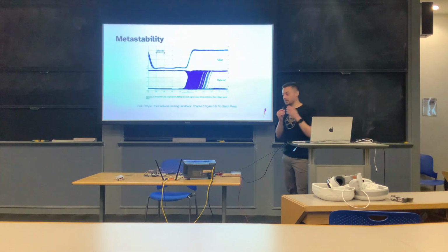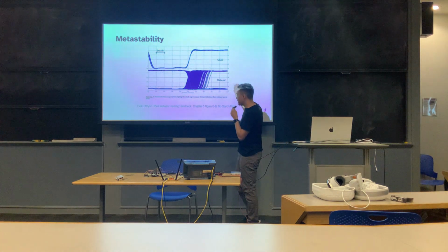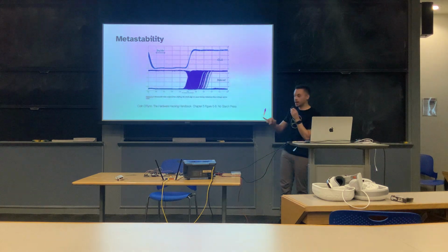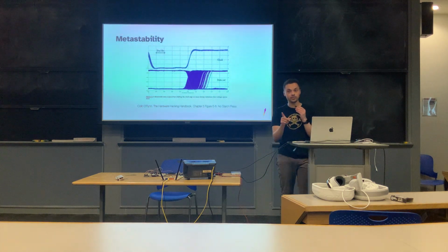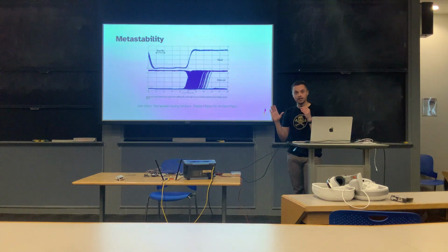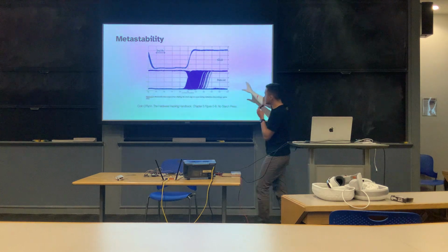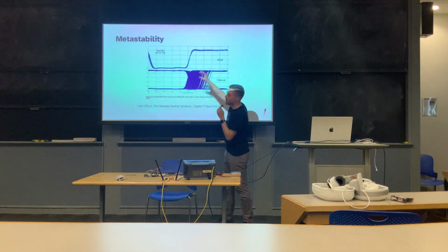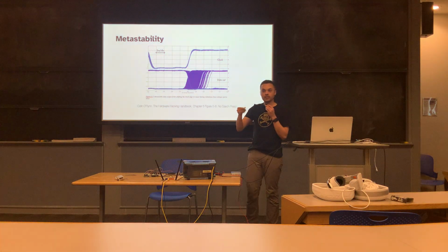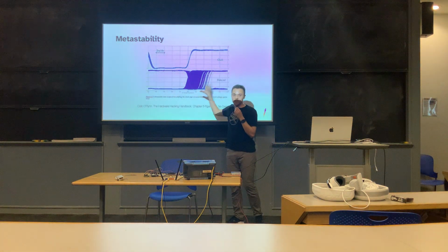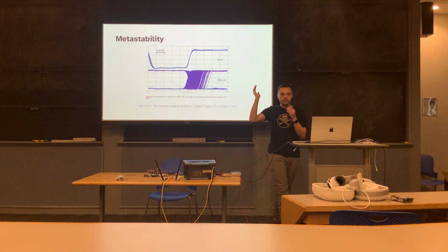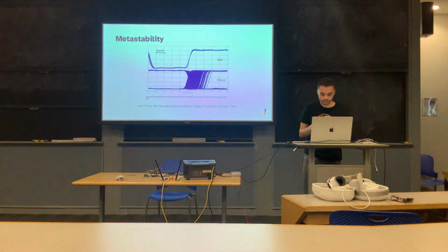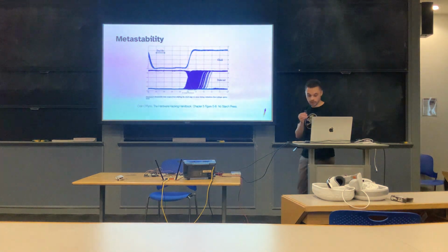So what does metastability look like? This is a screenshot from Colin O'Flynn's excellent book, The Hardware Hacking Handbook, which you all have access to through O'Reilly. I highly recommend checking it out. You can see here, when the clock goes from 0 to 1, if we violate the setup or hold times, we just kind of do whatever. Metastability is induced and you have no idea if it's going to be a 0 or 1. So that's what happens when you mess these up.